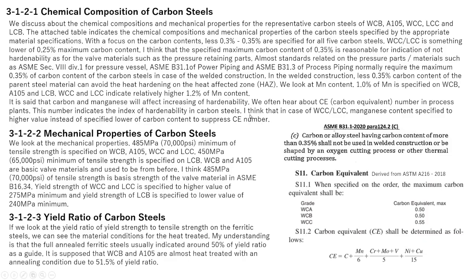I think that in the case of WCC and LCC, the manganese content is specified to a higher value instead of a lower carbon content, to suppress the carbon equivalent number.